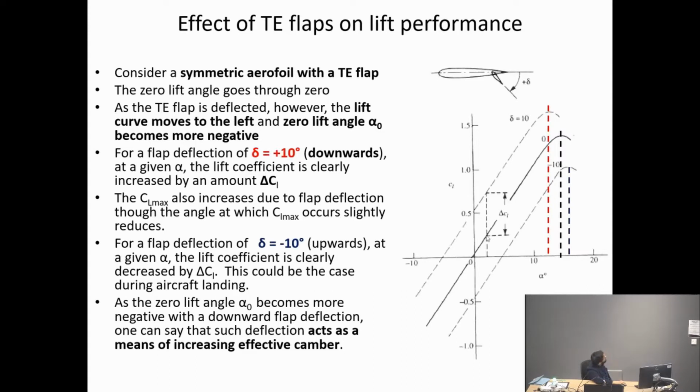So you can see, at a given alpha, let's say here, my lift coefficient is here. Using the flap deflection, you can see it goes from here to there, so by an amount delta CL. All right, and that's what it does.